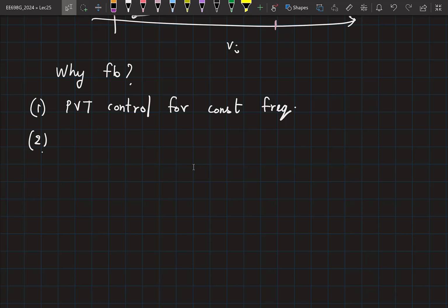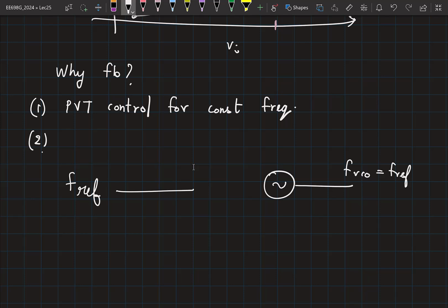So you're talking about some reference frequency, right? So is our aim to make sure reference frequency somehow controls the VCO, such that the VCO frequency is same as the reference frequency? Not necessarily, is it? Then what happens? So you can adjust, sorry, you were saying? Harmonics of FREF. Okay, so basically multiplying FREF by some integer, right? We didn't form the structure. FREF is the reference input frequency.